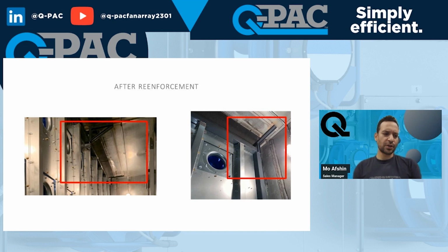There was another question regarding when we recommend using reinforcement. Again, if you're going to combine multiple bulkheads, so if this is a system that goes beyond that 280 inches, then we have to provide you with multiple bulkheads. Between those two, we recommend similar reinforcement: weld a structural beam, a 4x4 beam, so that your structure is supporting both of those bulkheads. But if it is one span of bulkhead, then you just need structure around the perimeter, so that the perimeter angle would go around.